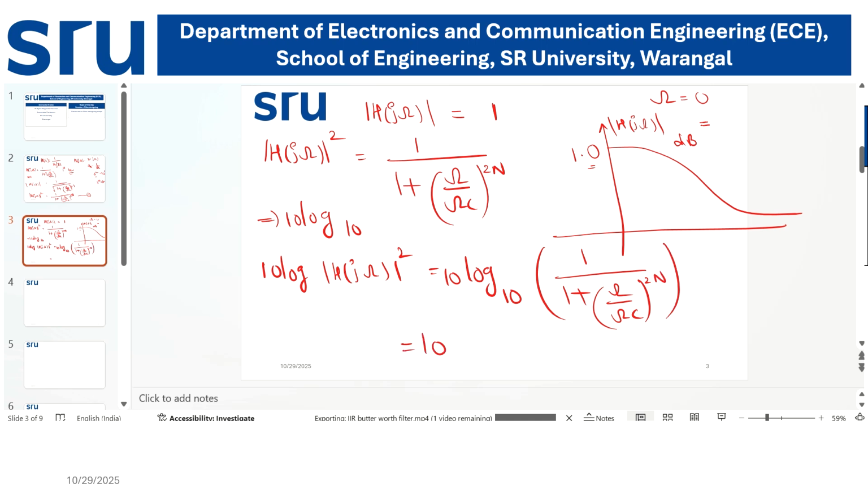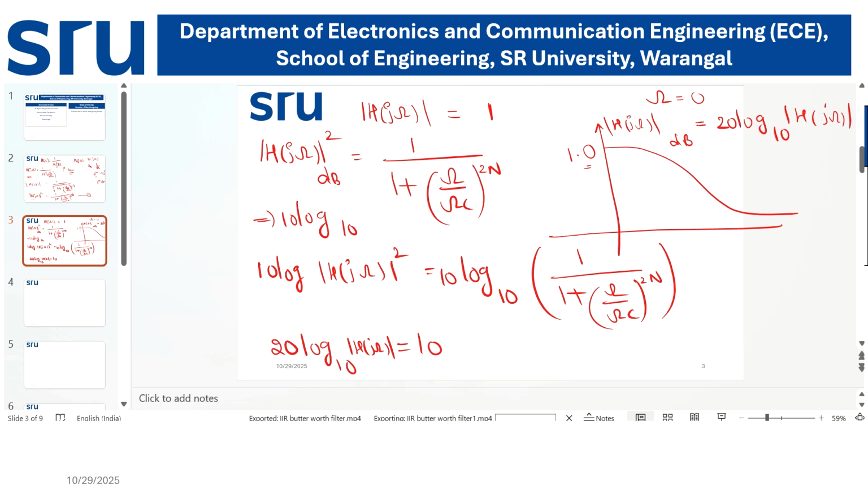The 2 goes to the front, so multiplying by 10, that is 20 log base 10 of the magnitude of H(j omega), which is equal to 10 log 1, where log 1 value is 0, minus 10 log of the denominator, 1 plus (omega by omega c) whole power 2n.